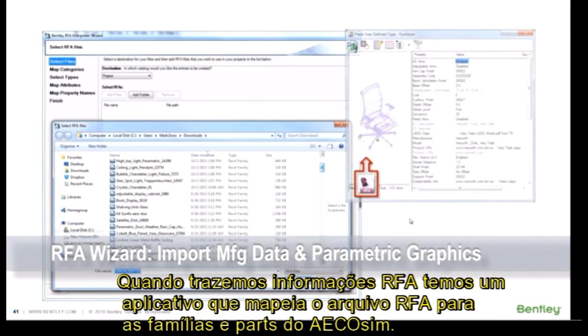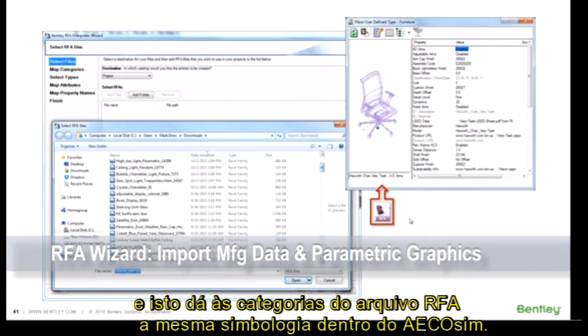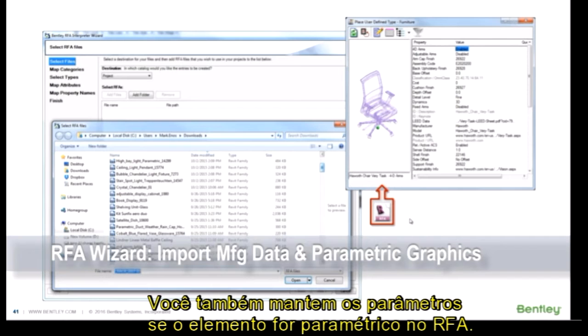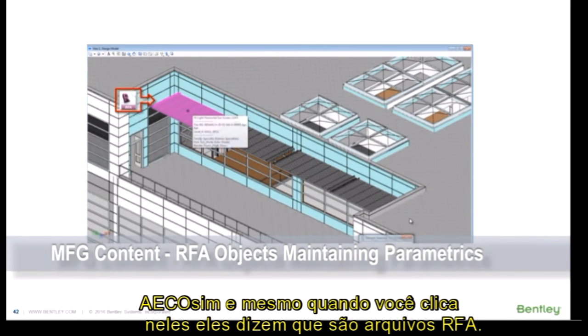When we're bringing in RFA information, we have a wizard that maps the RFA file to the Building Designer part and family. So that gives it all the symbology that it's going to be on the right level in the model: level, color, line style for the drawing and the 3D model. And it also maintains parametrics if there are parametrics in the RFA. In this example, this is a solar screen that was brought in through the wizard and placed in Building Designer. And even when you click on it, it tells you it's an RFA file.